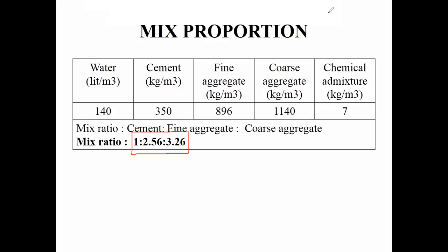Okay, so we have successfully discussed the mix design procedure when we are using superplasticizers. Next, we are also going to discuss mineral admixtures. That is, we are going to replace the cement, right? If it is a chemical admixture, you are going to replace water. If it is a mineral admixture like fly ash or silica fume, you will be replacing the cement content. So we will be discussing that in the next coming classes.